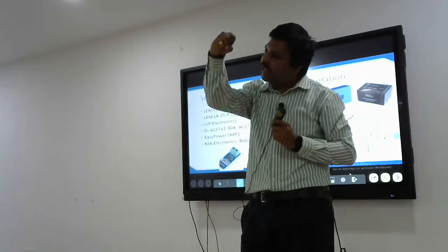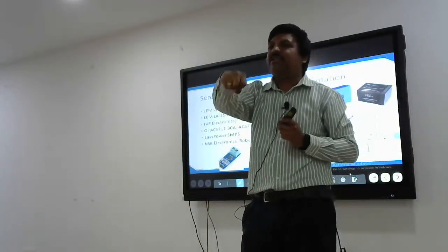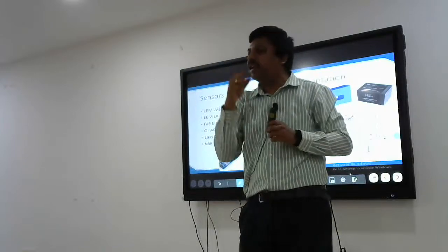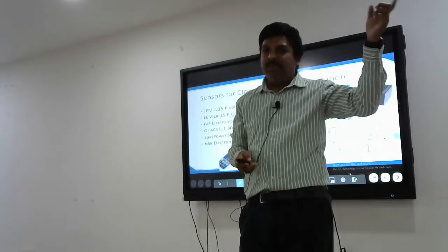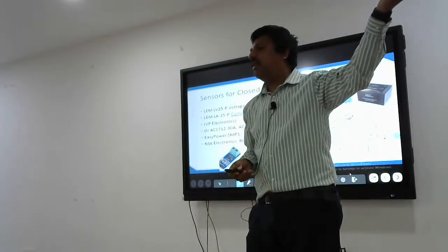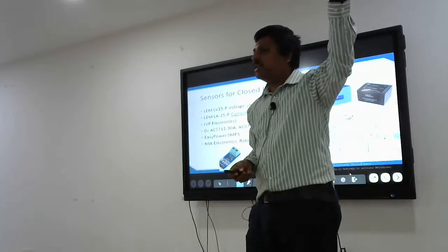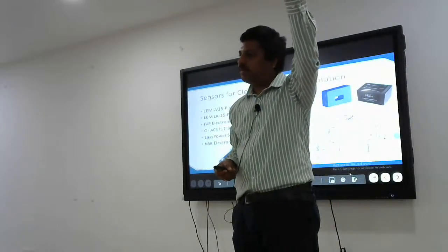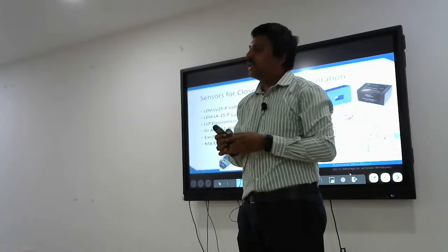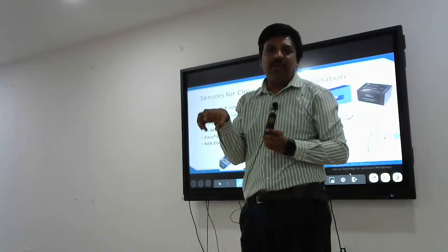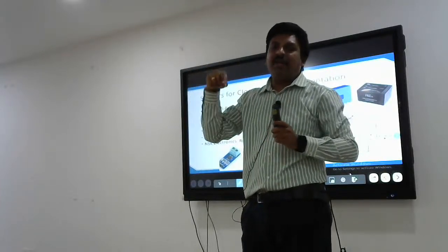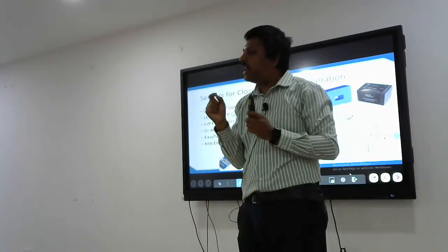The temperature sensor understands that the room temperature is 27 degrees, so you turn on the AC and the compressor will be on. When the compressor is on, the temperature will decrease from 27 degrees to 24 degrees. Then the compressor waits till 23.